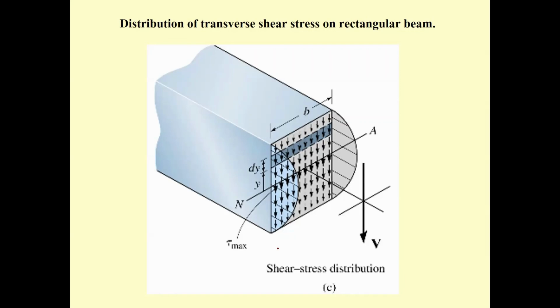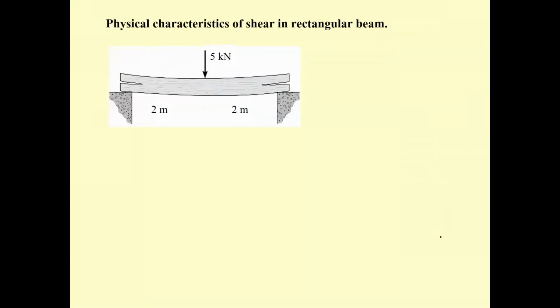Okay, let's see. This is what I'm saying to you. For the rectangular section, the maximum occurs here, and the maximum here is tau max equal to 1.5 Vmax divided by A. I would like you to remember this one because we will use it a lot in the design of the beam. And this is the crack at the end of the beam, which I explained already.